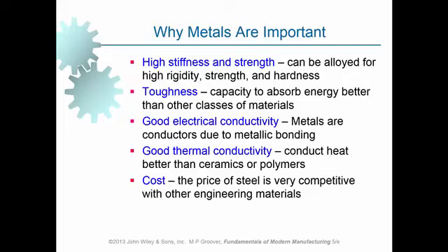Appearance, they look nice. For example, the body of the car. Why is it made of metallic material? Because it's quite smooth, strong at the same time, and it is convenient to be used in order to make the body of the car, the panels and that sort of stuff. Suppose that we don't have a metallic material available and we want to make the body of the car making use of another type of material. Ceramics would not be a good choice because they have got high density and they are brittle as well at the same time.